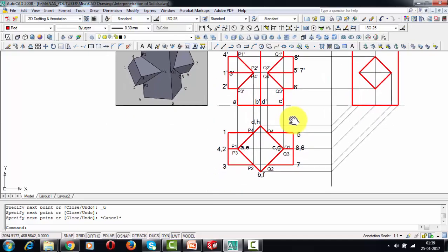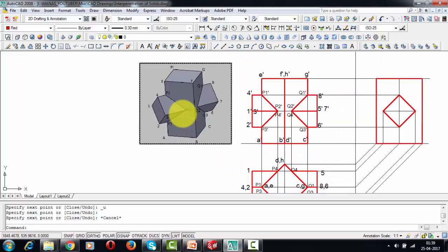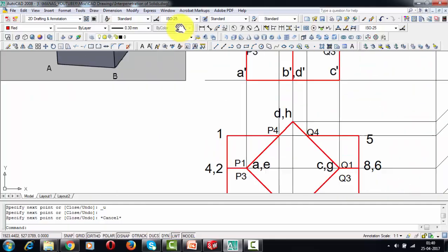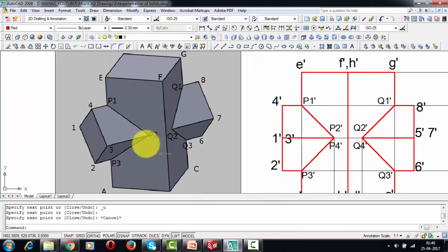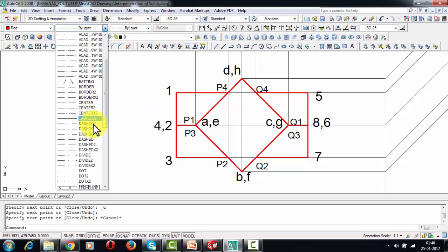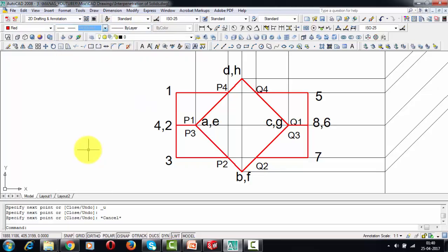Okay, we're almost done, with a few modifications yet to be carried out in the form of hidden lines. Okay, now a small portion from P1 to Q1 of this edge 48. It's not going to be visible, but we have to give it some respect in the form of creating a hidden line. From P1 to Q1, we've got to make this line. So right now I'm going to be erasing this portion, and I'm going to be using a lighter line, a red color line in fact, but a different sort of a line, a hidden one.